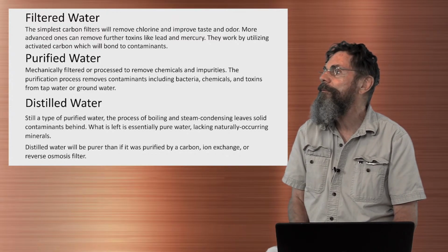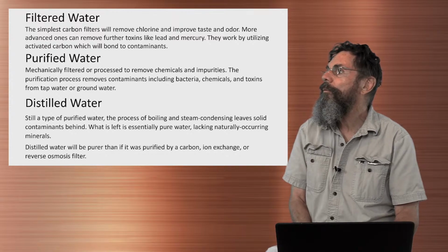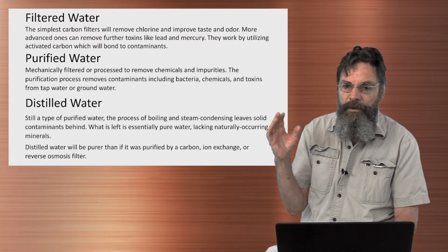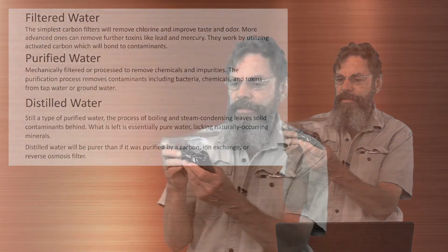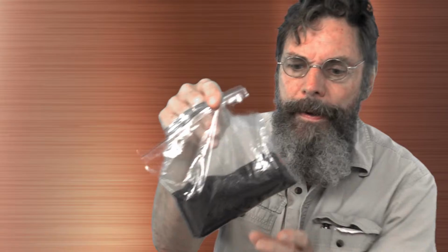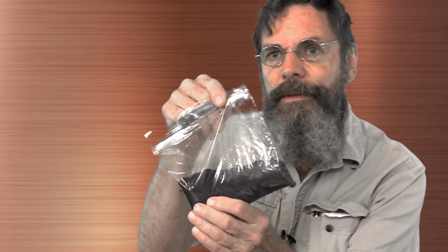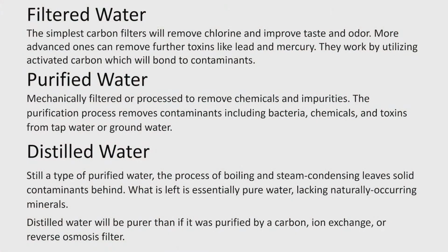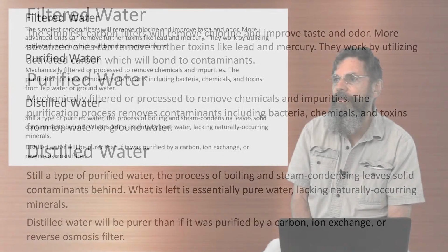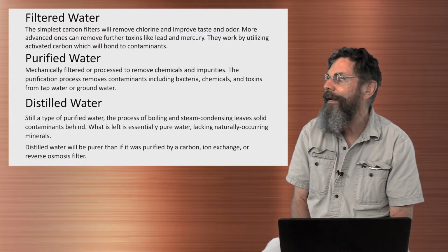So what I said was activated carbon particles will bond to the contaminants, and the pure water will pass through. So the activated charcoal is basically a very, very fine powder, and I've just got a little bag of it here, granulated, very, very fine. And actually, it doesn't stain. You would think it'd leave big black marks that you have to wash out, but it's really not sticky like that. By the way, activated charcoal becomes activated by heating it to an extremely high temperature. I think it's probably around 1700 degrees, and it creates air pockets and cavities within the charcoal structure. So it's then called activated.